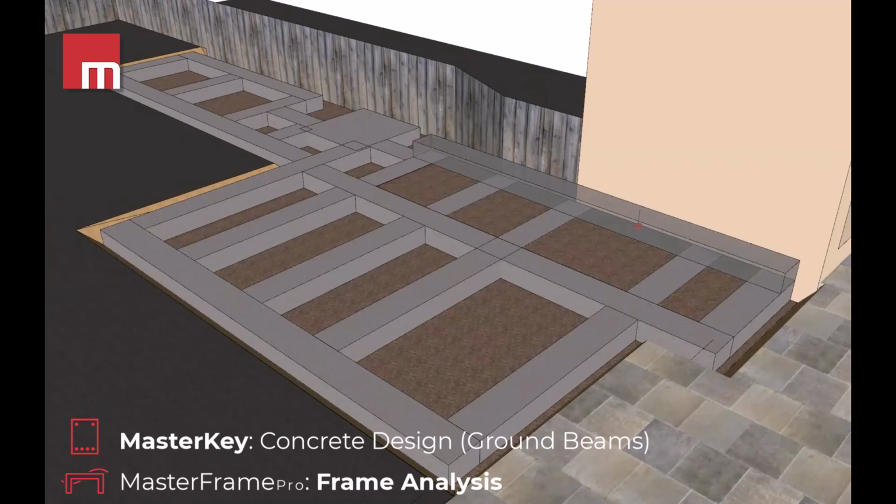The ground beams shown here are mostly 900mm by 600 deep grade D35 concrete, and they are detailed to include 75mm cover below to allow the piles to sit within and run continuous. So the ground beam closest to the neighbouring property, running parallel, as you can see there, is set higher and is supported by the lower ground beams that were installed during that hit and miss sequence.